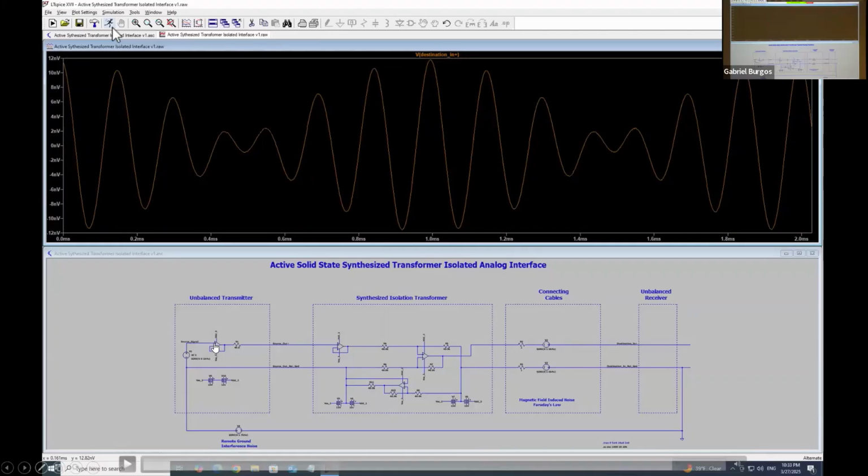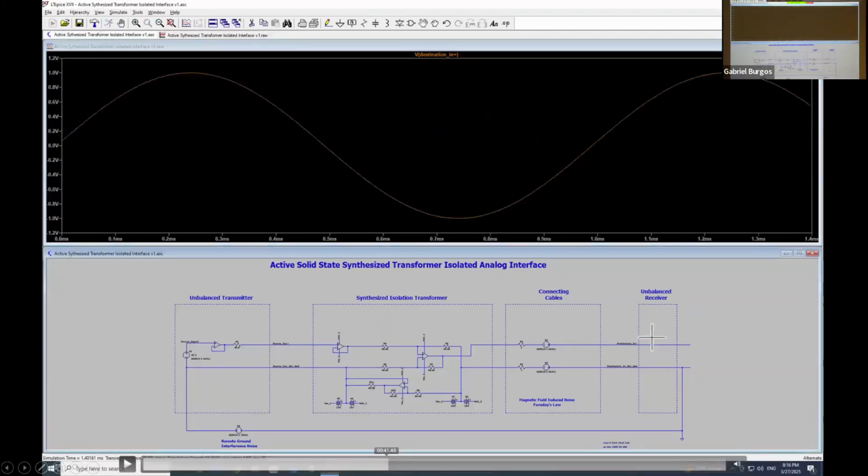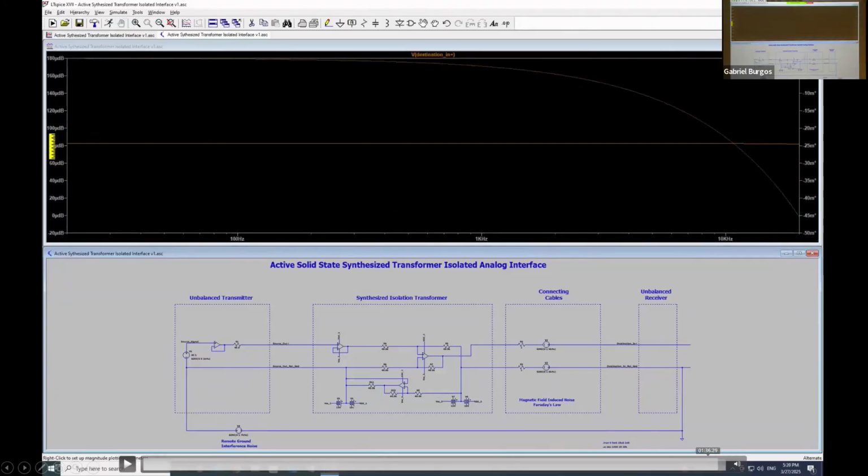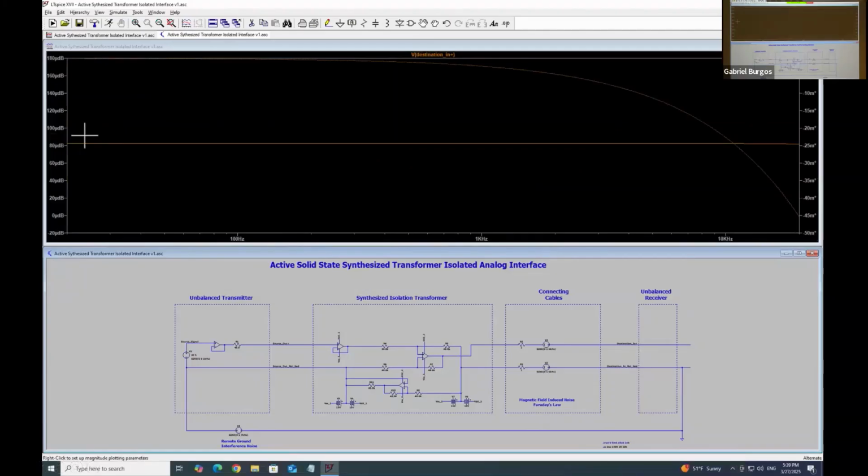The input signal is, let's see, show a picture of that. There's the input. I think that's the input signal, right? And then we have the noises. I put the input signal at 1 kilohertz. I had the noises at 6 and 7 kilohertz, so that they would interfere with each other, and you can see how ugly that looked. And then it all goes away, and we end up with what's essentially a mixture of those two sources of noise at various tiny levels. So anyway, I demonstrated that circuit with LTSpice and can prove analytically that it works.